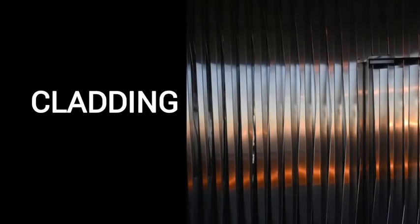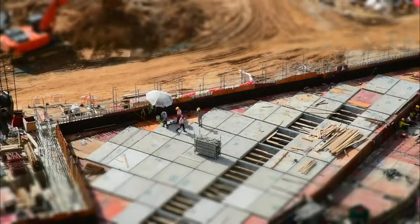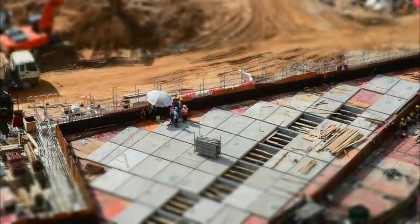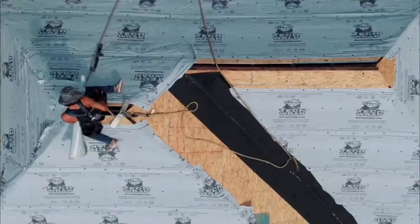Then we have specialty materials. These serve specific purposes like insulation and waterproofing. Yes, we have something called the damp-proof membrane. It's a membrane that stops capillary action from the floor, the mass concrete floor slab, and that membrane is a material.